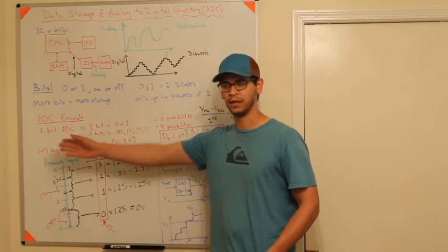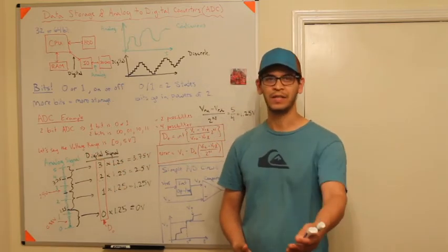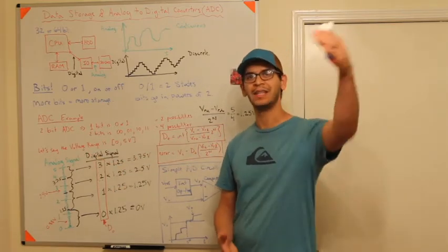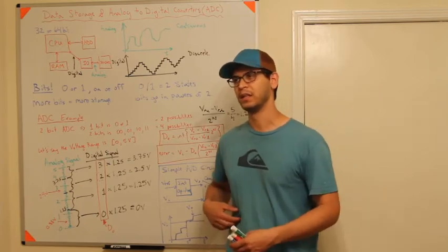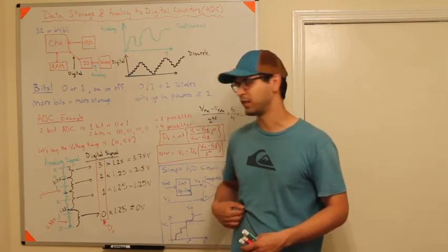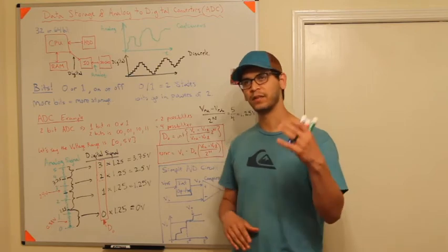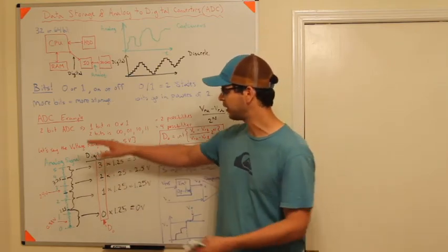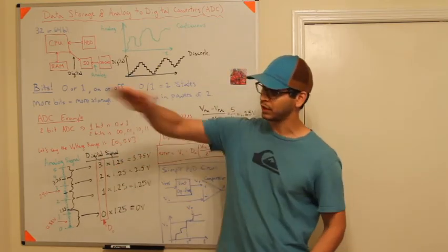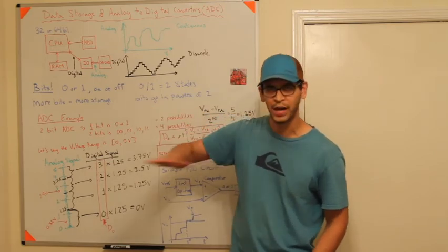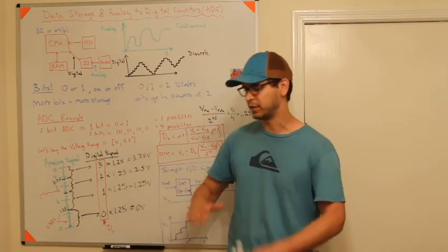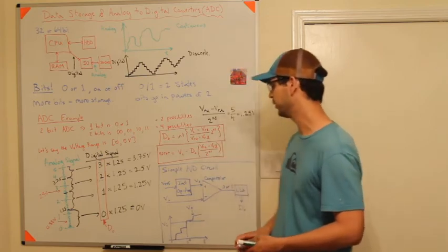Absolutely not. And if you look it up, Arduinos have a 10-bit ADC. So that's 2 to the 10th power, which I think is 1024. And so that means you have 1024 possibilities. So you're going to take 0 to 5 volts and slice it into 1,000 little bins, which means you're going to be a heck of a lot more accurate.